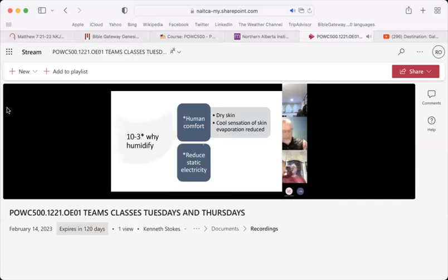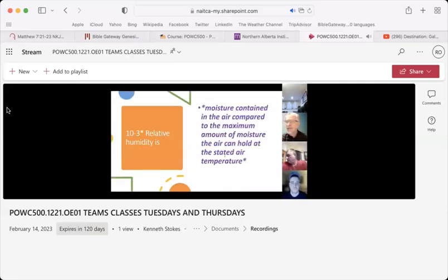Okay, why do we humidify? So review of chapter 10. Why do we humidify? Mostly for human comfort. Dry skin can be a factor. When humidity is high enough in a heated building, people will feel warmer at a lower temperature. So the cool sensation of skin evaporation is reduced, and also important to reduce static electricity.